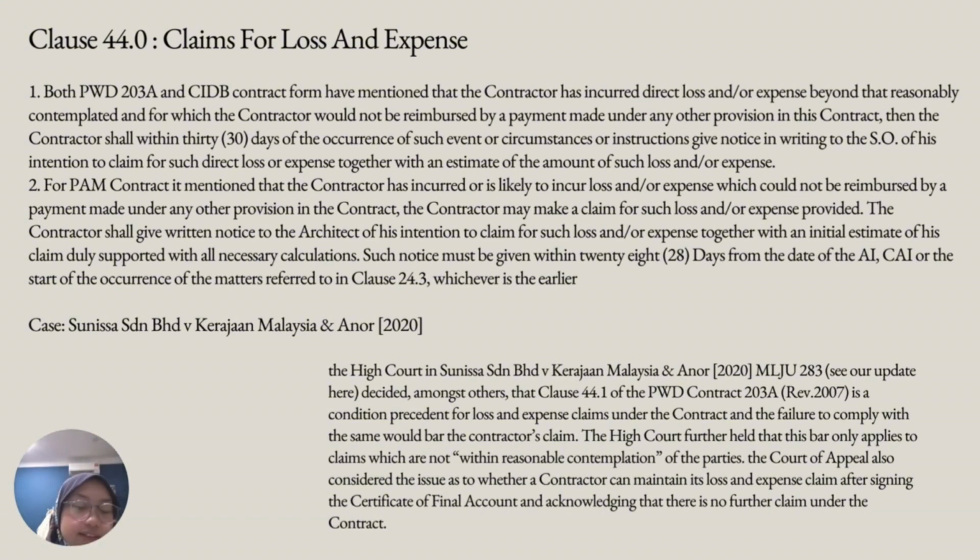Case that related to this clause is Sunisa Sdn Bhd versus Kerajaan Malaysia. The High Court in Sunisa Sdn Bhd versus Kerajaan Malaysia decided among others that clause 44.1 of the PWD contract 203A is a condition precedent for loss and expenses claim under the contract, and the failure to comply with the same would bar the contractor's claim. The High Court further held that this bar only applies to claims which are not within reasonable contemplation of the party.